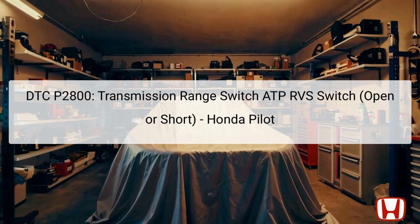In this presentation, we will be focusing on the Diagnostic Trouble Code DTC P2800, which pertains to the transmission range switch ATP reverse switch, also known as the RVS switch, for the Honda Pilot models from 2016 to 2022. This particular error indicates an open or short in the electrical circuit associated with the transmission range switch. It is crucial to understand that this issue is related to the electrical system and not a mechanical fault within the transmission itself. Therefore, our troubleshooting will center on the electrical components involved.